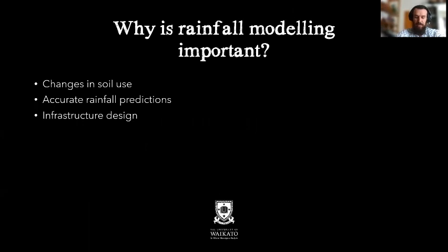Where previously there was pastures, hills, and valleys, now there are impermeable roads and houses for which the water, which would normally be stored and slowly make its way into the river, now is being restricted on these impermeable layers. To counter this, we design infrastructure which can handle the water and move it from these impermeable layers to the river or outlet. To ensure that the system is not under or over designed, a solid understanding of the relationship between rainfall and runoff is essential.